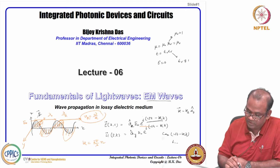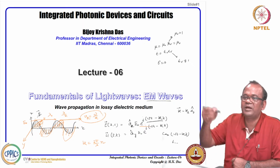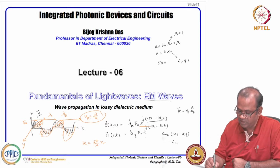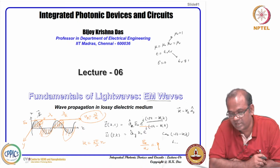And the interesting part is that the maxima, as it travels, does not change E naught; it always comes back to E naught, varying from plus to minus E naught. The magnetic field varies from plus to minus H naught. Obviously, E naught and H naught are also related by eta. That is what we learnt in the previous lecture.